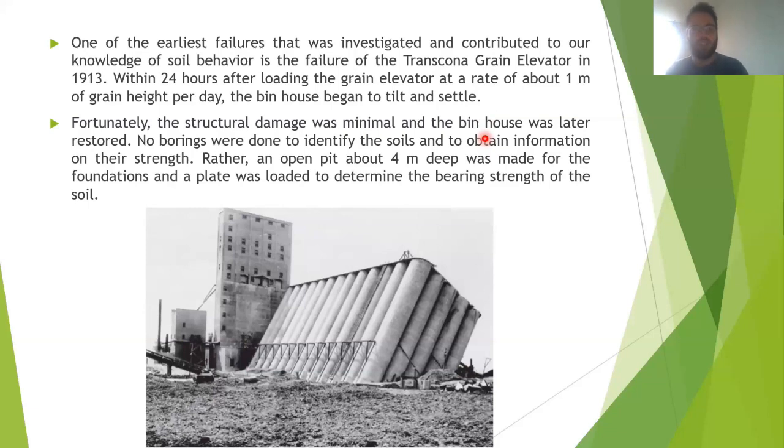That's huge. So what you do there is, first of course, the soil investigation, and based on soil properties, if you have really good soil, it can take a 4 meter depth of excavation, but you need to make a wide opening of the pit, because you cannot have vertical excavation everywhere, because it's just going to collapse.